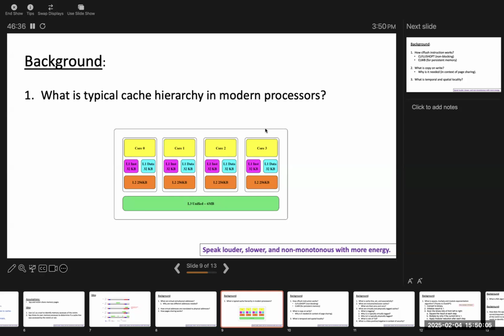Would that mean you'd have to split the two apart in real time, processing the instructions and the data differently? Yeah, it means that at the same time, you can read instructions and data. If you have only one L1 holding both instructions and data, then at a given time you can read only instructions, or you can read data. When you split, you allow read operations to be performed on both at the same time.